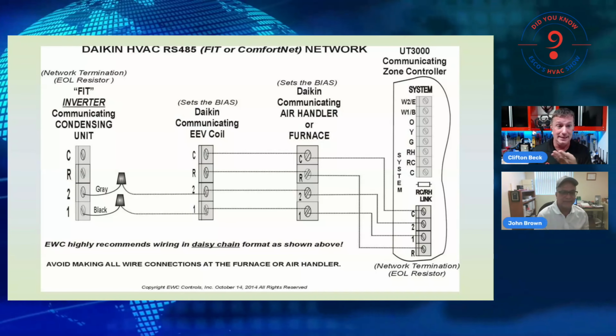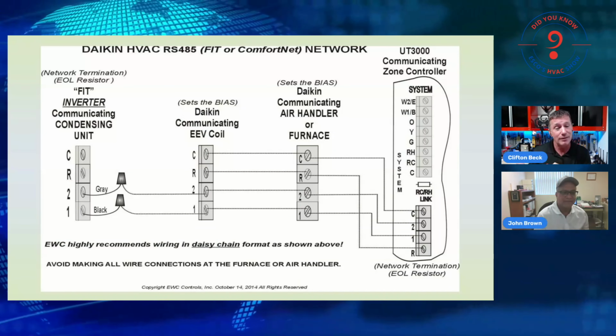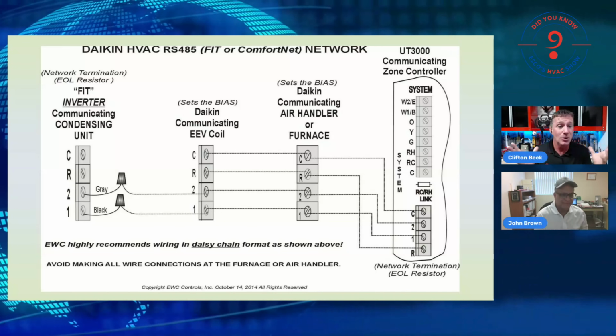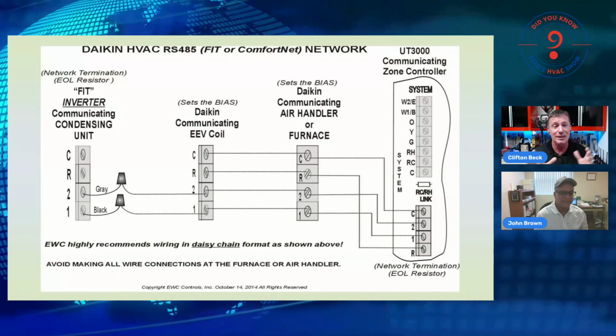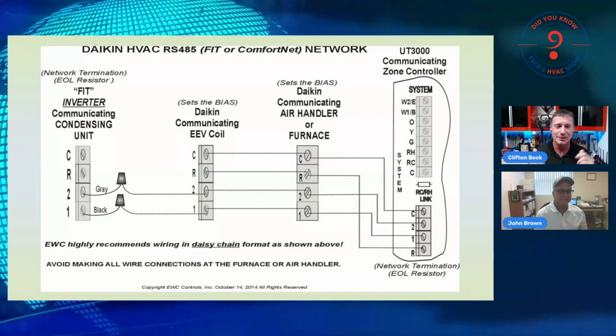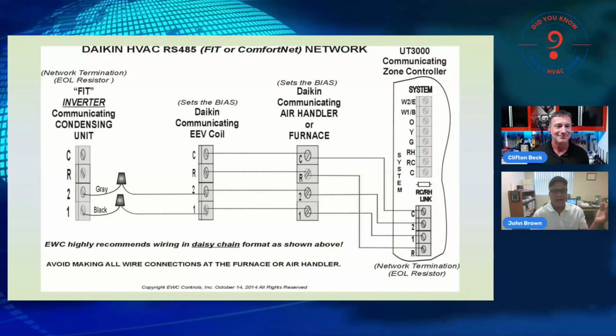Well, exactly. Doesn't it make sense just to put it at the electronic expansion valve and let the process begin at the component that does the metering? So if we know the system is functioning properly, we can read superheat without even putting a set of gauges on.